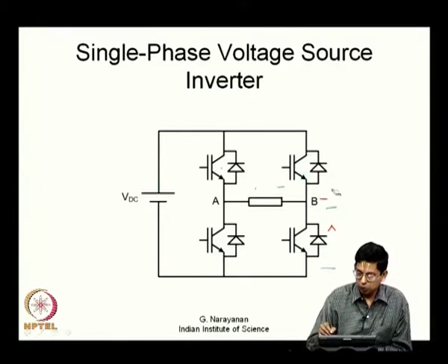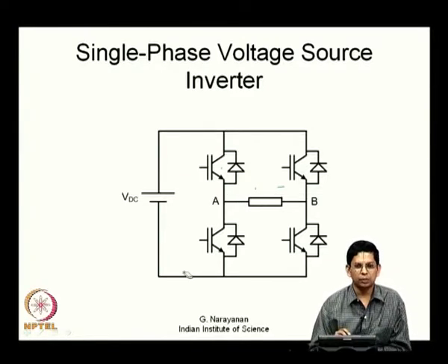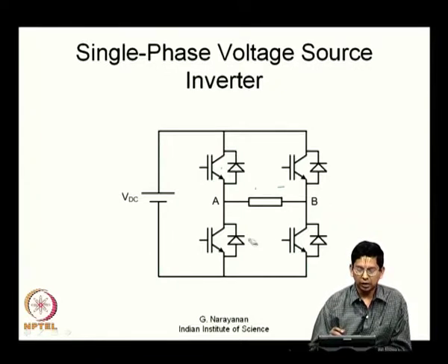So, now you have a voltage source inverter which has been realized using some transistors or IGBT let us say with anti-parallel diodes. This is what you have now. Such devices are commonly available and voltage source inverter is very popular these days. So, we will look at how to do further control etc., as we go about now.